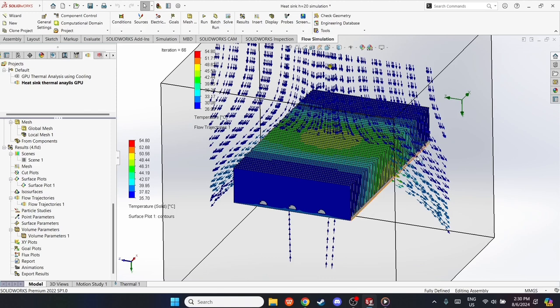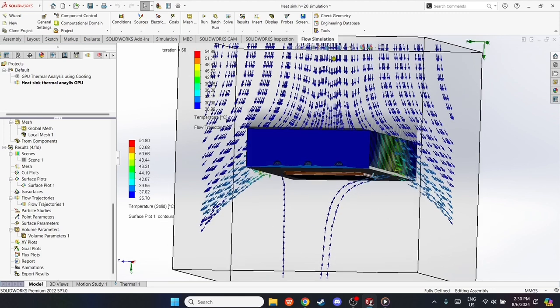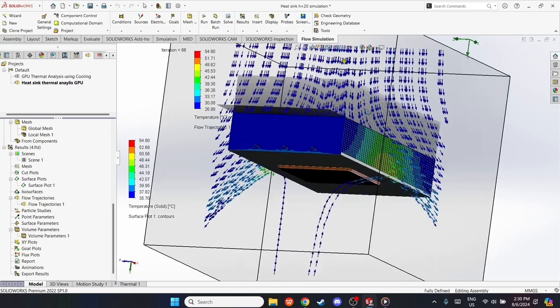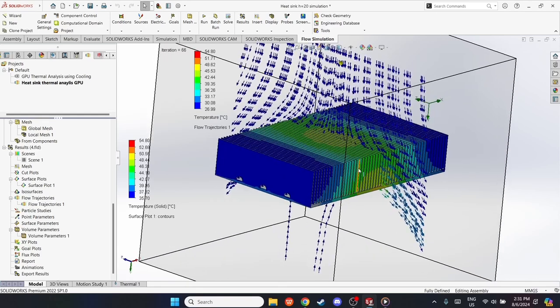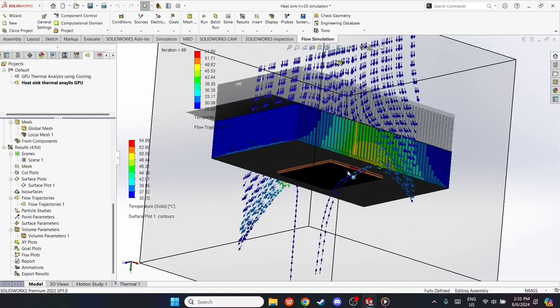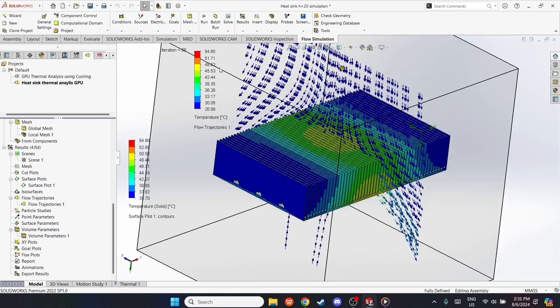Today I'll be representing my group to present the outcome of the heat transfer simulation. Our main product is the GPU heatsink, which consists of two main parts: the main heatsink and the plate. These two main parts are made of two different materials. The bottom plate is made of copper, which has an extremely high thermal conductivity of 390. This high thermal conductivity helps transfer all the heat from the GPU board into the heatsink so that the heat can be dispersed.